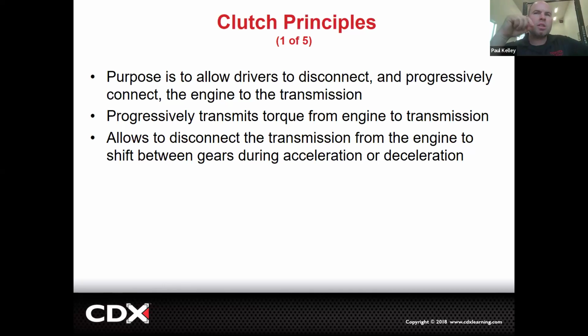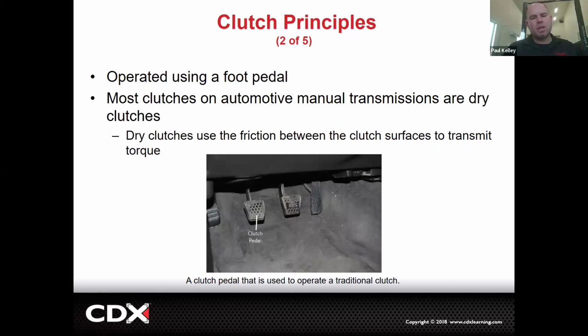When we get into the actual manual transmission transaxle, the first step in performing a shift is to disconnect engine power. The way we disconnect engine power, we depress the clutch pedal, which disengages the clutch, and then there's no torque going through the input shaft. And then click, click, click, we can shift gears. Cool. So there's some basic stuff.